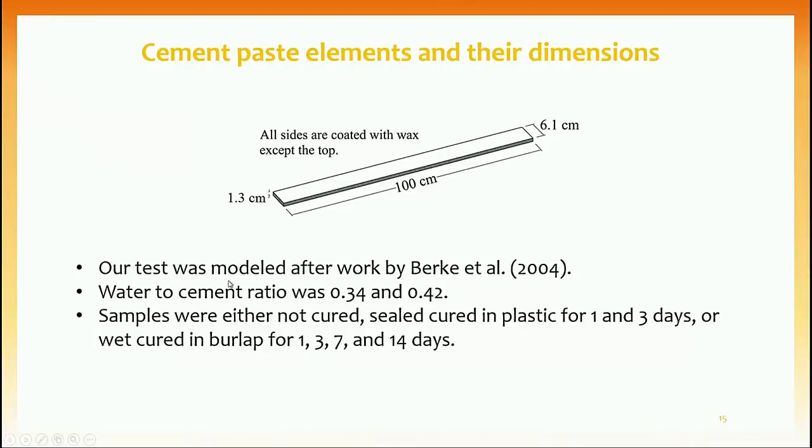And the test was modeled after work by Berg et al. in 2004. We used different water to cement ratios, and we used different lengths of wet and seal curing: 0, 1, 3, 7 and 14 days of wet curing, and 1 and 3 days of seal curing.